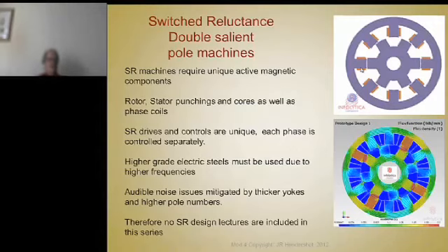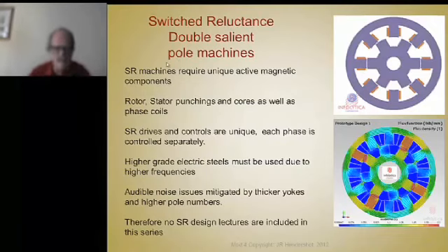If everything else is equal, same torque, same diameter, same voltage, everything, the one at the bottom is going to be quieter than the one at the top, with the same yoke thickness. The deflection is way less. It's much stiffer because of the arc length between 90 degrees and 180. So the effective section modulus against that deflection makes it quieter.